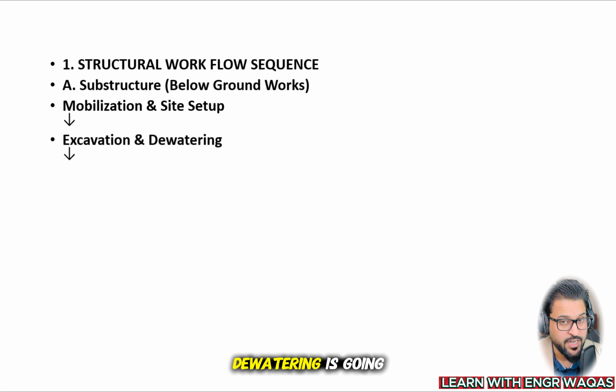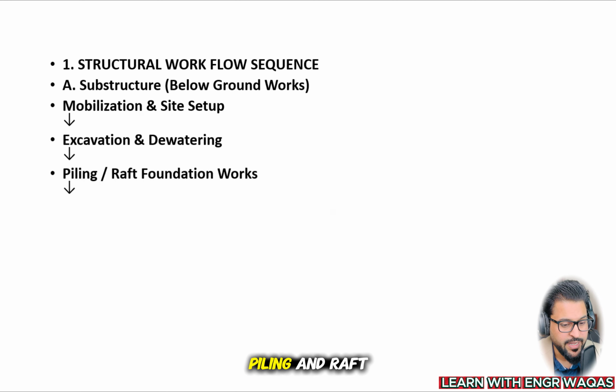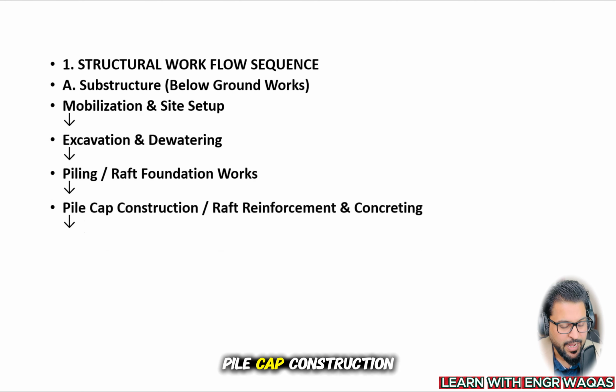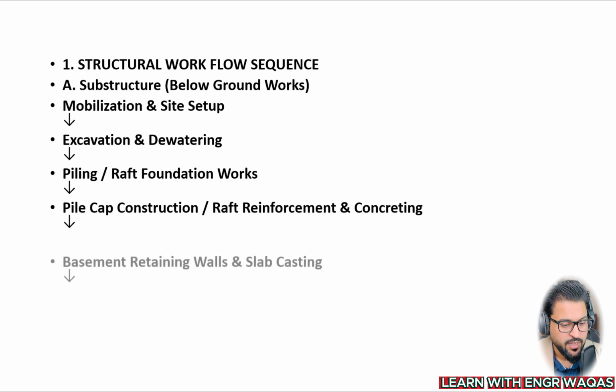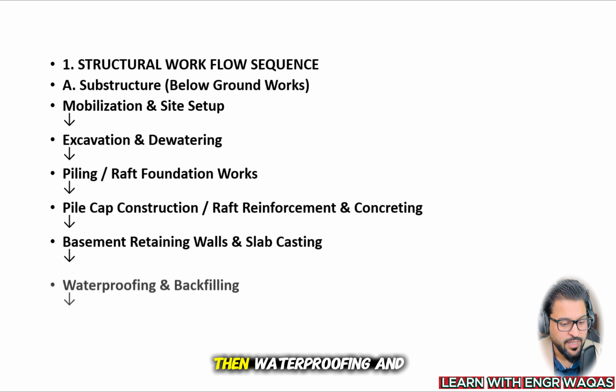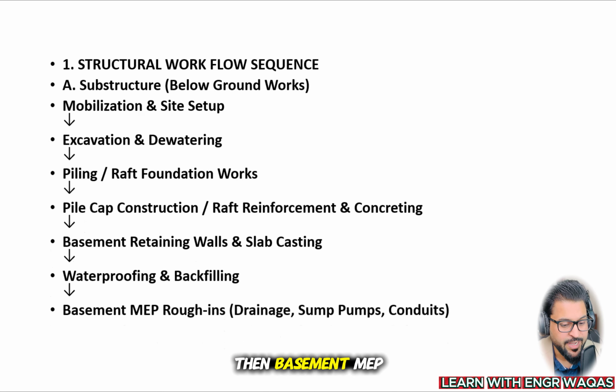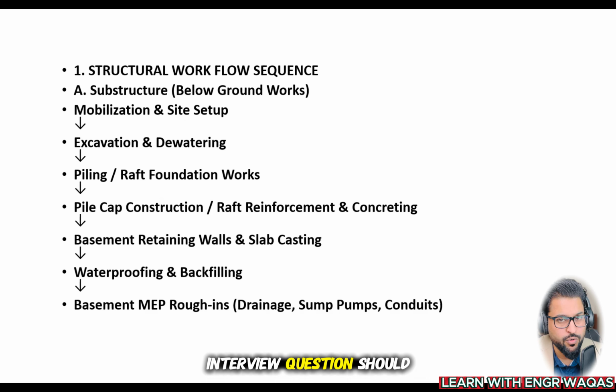Then excavation and dewatering is going to drive piling and raft foundation works, pile cap construction and raft reinforcement, then basement retaining walls, then waterproofing, and then basement MEP rough-ins, drainage, sumps, and conduits, which I believe strongly that we have gone through this project schedule randomly, like MEP rough-ins, drainage, sumps, backfilling, dewatering, and each and every. So that flow chart, just memorize and try to learn how this job interview question should be answered in the shape of a flow chart.